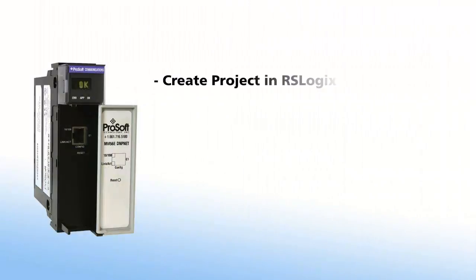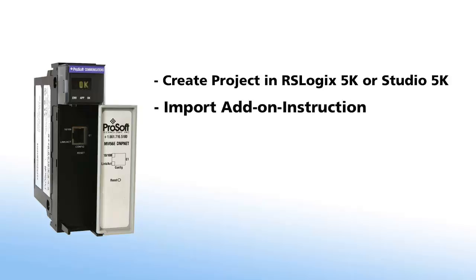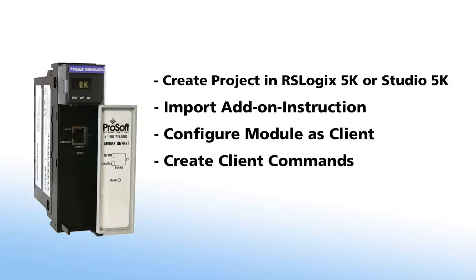In this video, we're going to create a project in RSLogix 5000 or Studio 5000, depending on your version. The steps are the same. And we'll import the supplied add-on instruction. We'll then configure the module as a client or a master to communicate with IEDs on a DNP Ethernet network. We'll create client commands for several different data types and simulate communication using ASE 2000. We'll wrap up by going over how to access the module's diagnostics using ProSoft Configuration Builder.